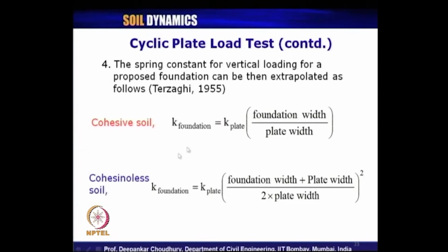In this manner we can easily find out the stiffness of our foundation to be designed, and then using this value we can further do our dynamic analysis, because in all our dynamic analysis we need this value of spring constant, which is one of the basic inputs we require. So, in a simplified manner we can compute the stiffness of the foundation.